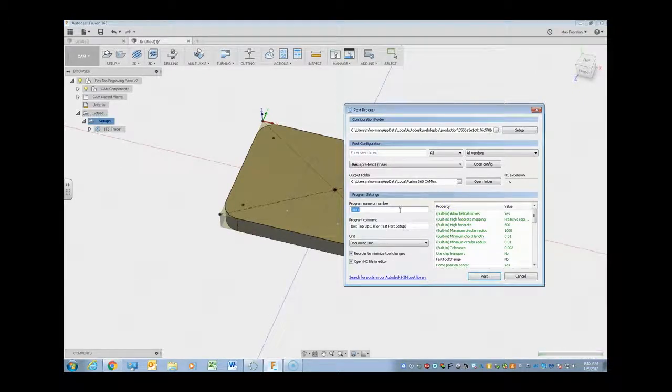Okay. Now what we'll do first is you've got to give this a program name. By default, it typically comes up with this 1001 number. I recommend that you change it from that default. This has to be a 4-digit integer number. So you could even use today's date, 0405 in this case if you wanted to, or your birthday, or some 4-digit number that you can remember. So just for kicks right now, 0405. It's just a program number that has to be a 4-digit integer. Okay. If it is not a 4-digit integer, it's going to give you an error.